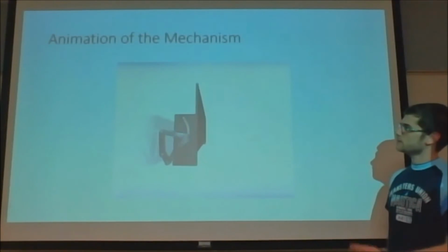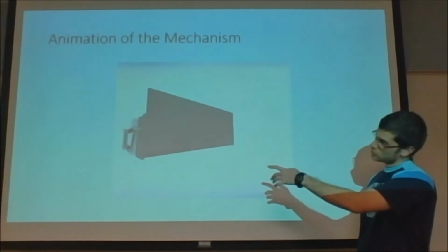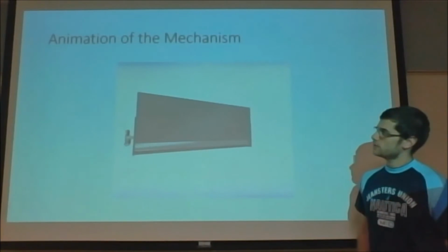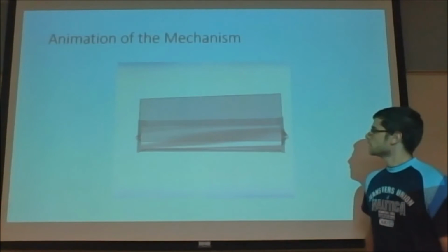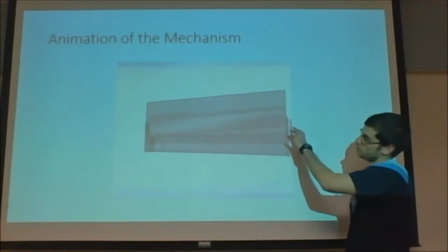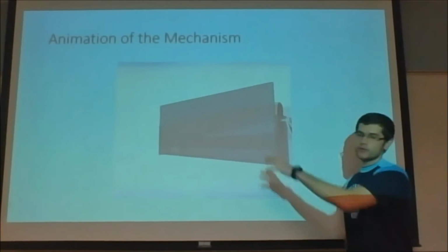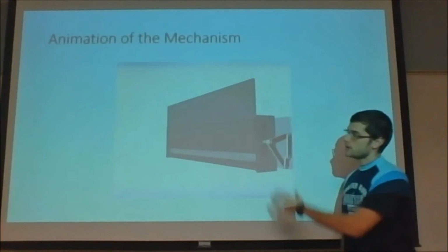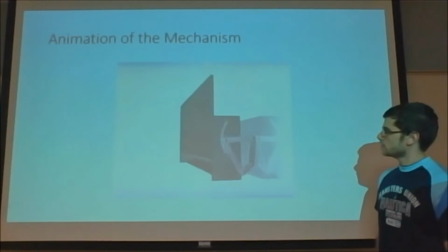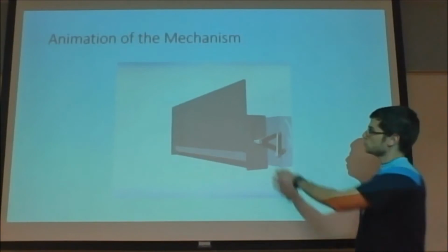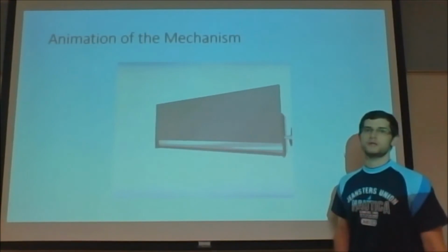This is a video representing the motion of the mechanism. You can see as link 2, which is the shortest one, goes through its 360 degrees of motion, the blade gets displaced up and down, and this motion will displace the water inside the channel, which will displace the water that's surrounding the channel wall, creating the artificial waves. And you can see that the motion of the slider of link 4 had to be maximized in order to achieve more displacement of water.